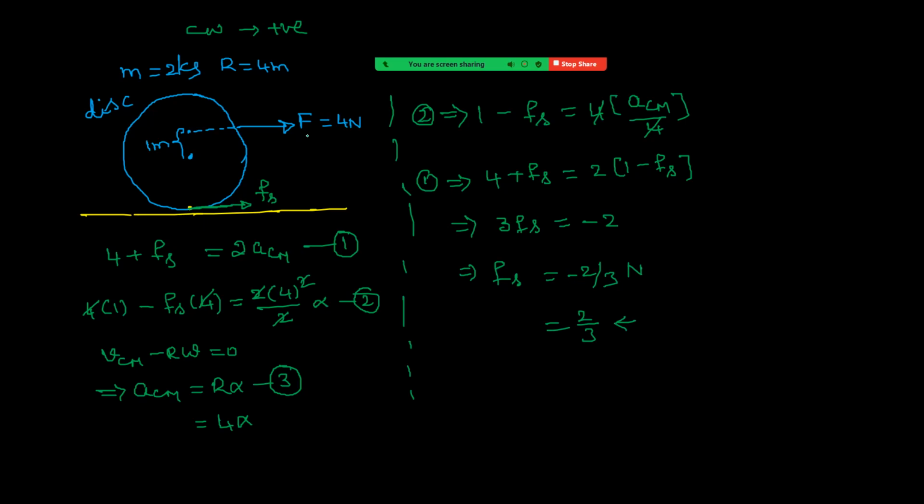Okay, so here we have to keep in mind that this frictional force depends on how much force is applied and at which location this force is applied. At which location this force is applied means for the same force, if you are changing the point of application, frictional force may change. Okay, let us do one thing. Suppose same problem. At what height must this force be applied so that no frictional force acts on the body?